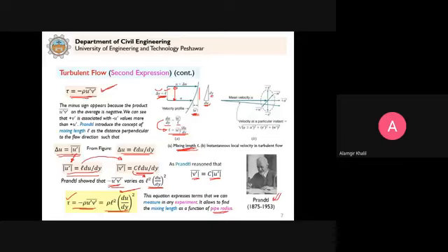You have the head loss, and from that we can easily calculate the pipe wall shear stress. Clear? And du by dy we can measure. Rho is the fluid property, so it means that we can express this L as a function of the pipe radius, and now in this equation all the quantities we can measure.